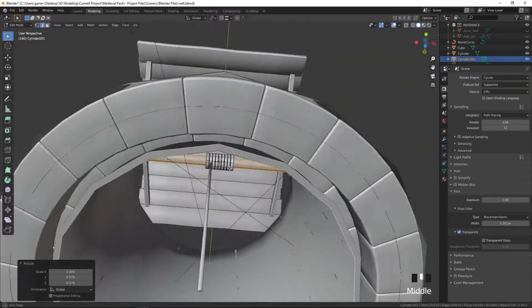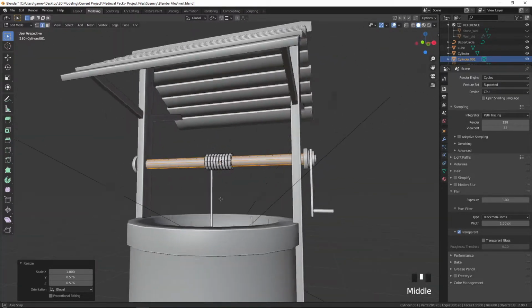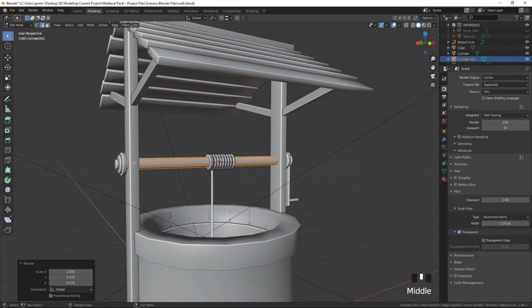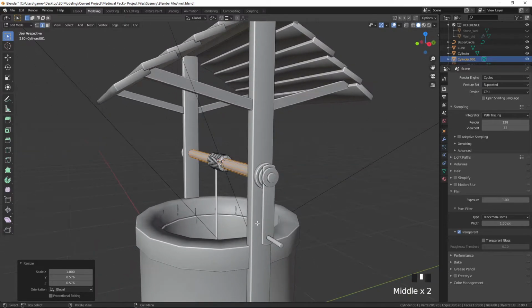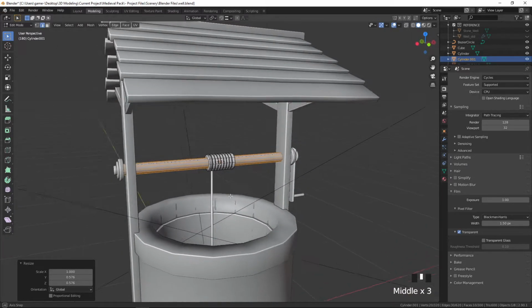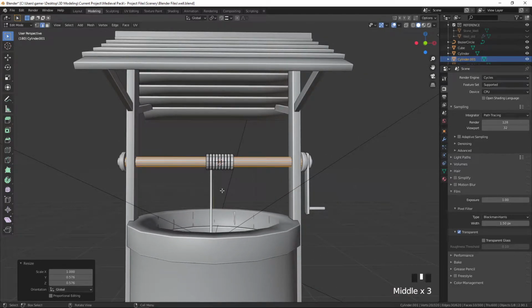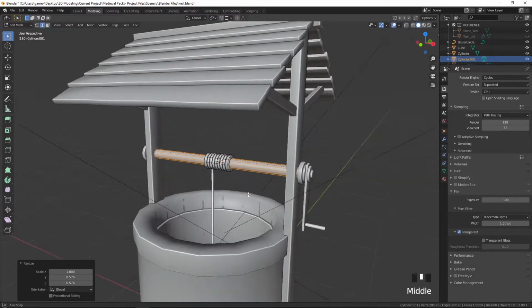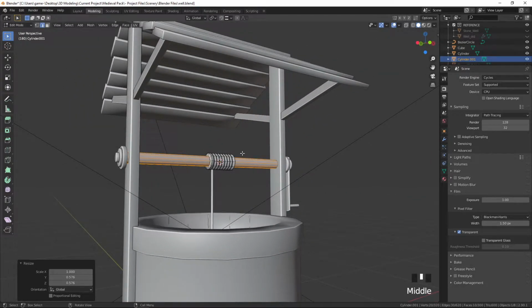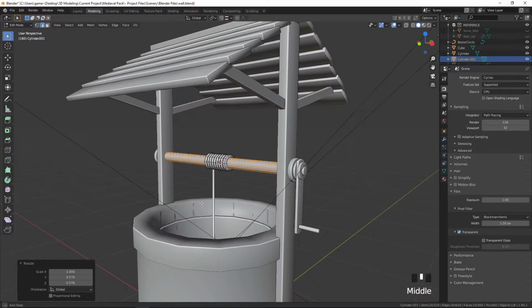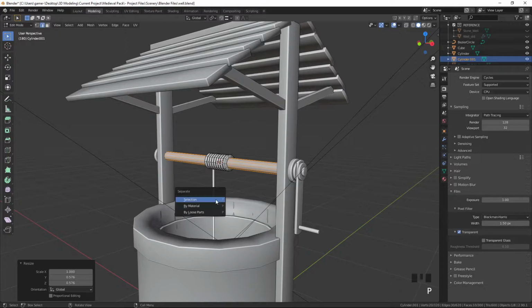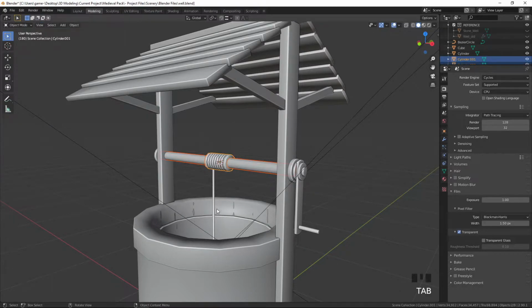So what I want to do to make it easier is use a mirror so that I can create this geometry on one side and it will copy to this side, and then we'll apply the mirror and I can add the extra geometry later. So obviously I don't want to do this while I'm inside the same mesh as other objects that don't need mirroring. So I will now, with the cylinder selected, press P, selection, and come out of that.